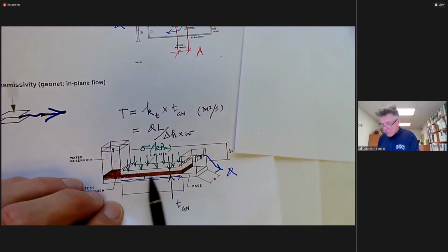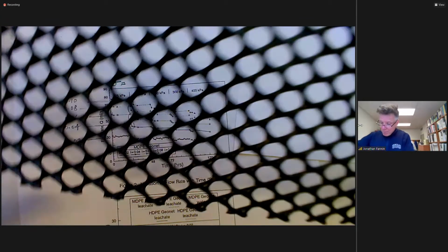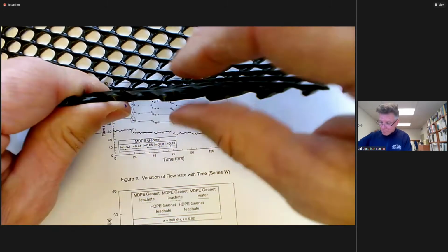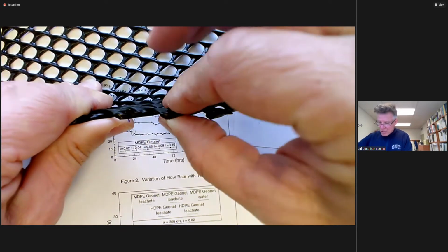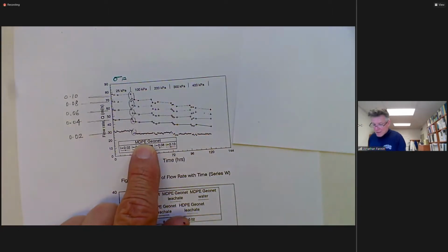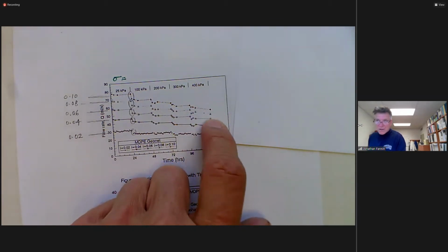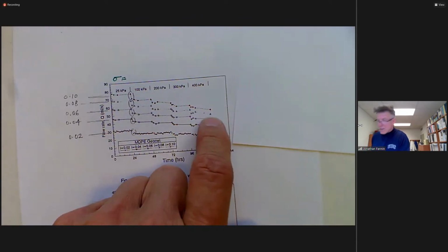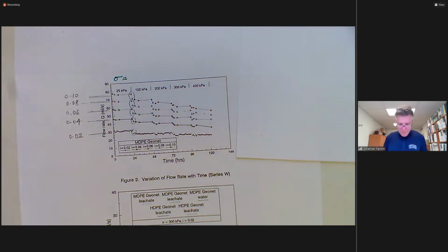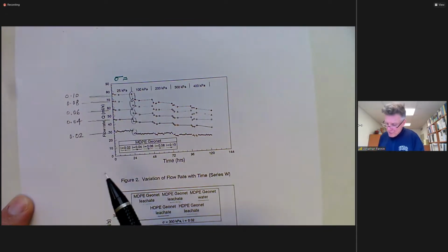And we're continuing to flow water through it. And can you imagine the specimen has a finite strength in compression, a function of the density of the geonet, and this is a so-called medium density geonet, but it'll have a crushing strength, and it would appear that we're beginning to perhaps get close to that crush strength. If I remember correctly, it was in the range about 500 to 600 kPa was the crushing strength of the material.